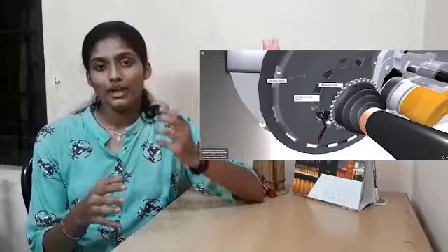Today, most cars employ a hydraulic braking system. The front brakes are considered more important than the rear because the car throws weight forward to the front wheels while braking. Based on this, disc brakes are employed at the front wheels and drum brakes are usually used at the rear wheels.